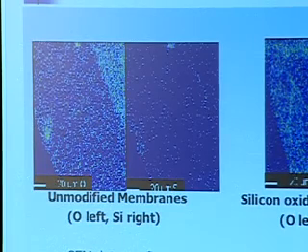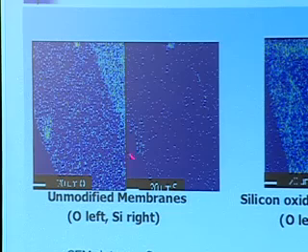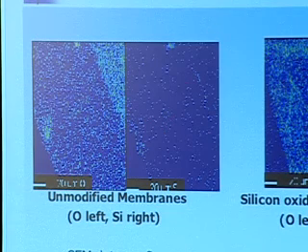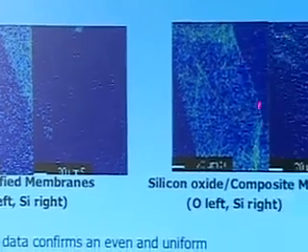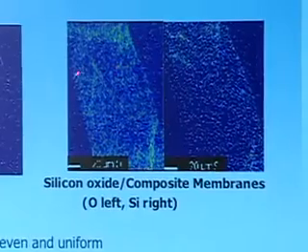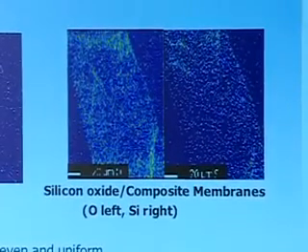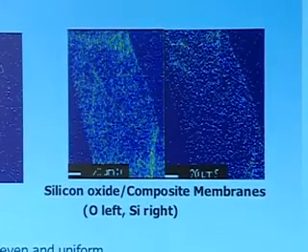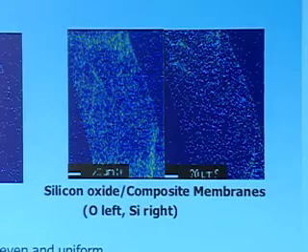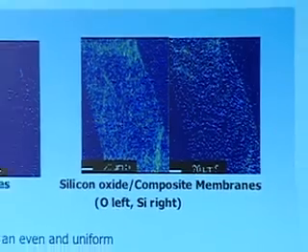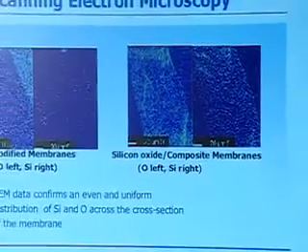On the other hand, if we look for silicon in this pure recast membrane, you can see you can't make out the membrane because there is no silicon in there. We take our composite membrane now, we look for oxygen, and you notice the green indicates there's more oxygen than the blue there in this map, that there's a lot more oxygen, and it's fairly homogeneously distributed in it. Not perfect, but fairly homogeneous. And we look for silicon, and we see a very homogeneous distribution of silicon in that membrane. So we can make the membrane just by mixing in particles, and it's extremely homogeneous.